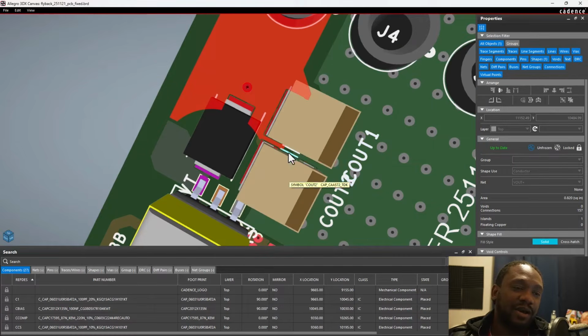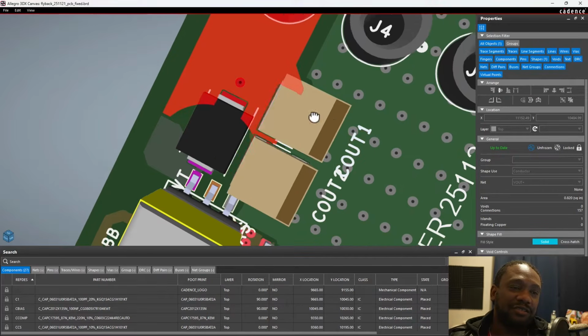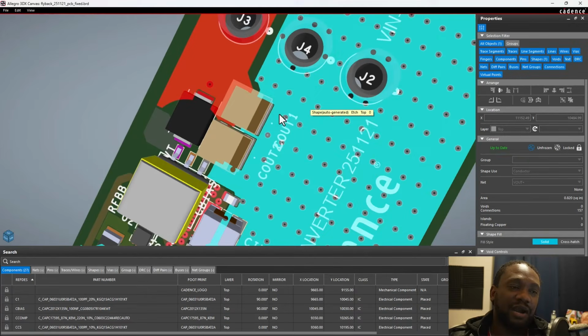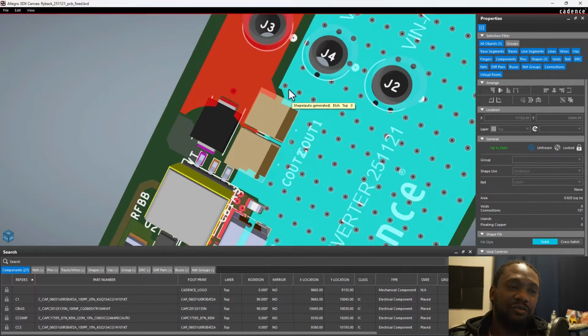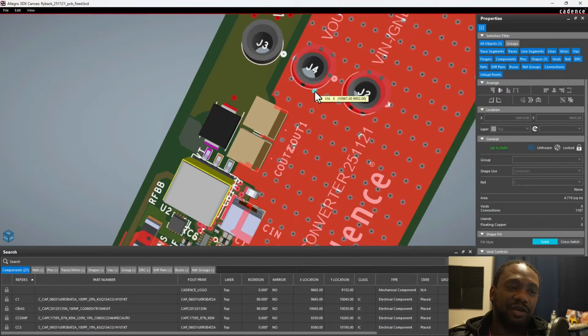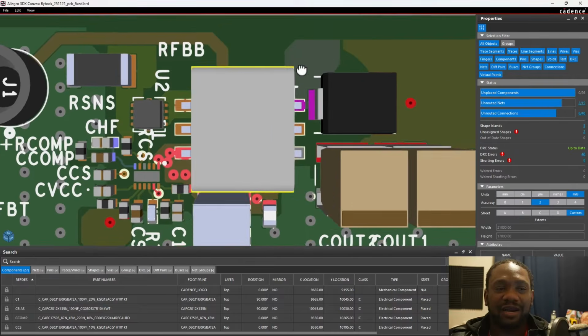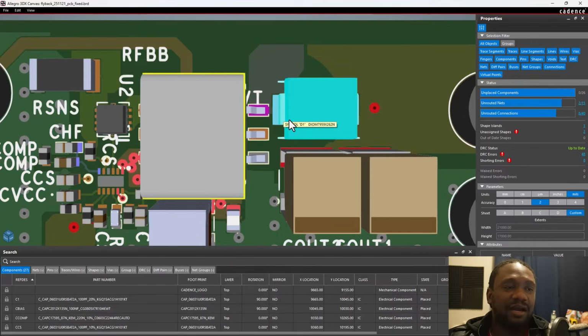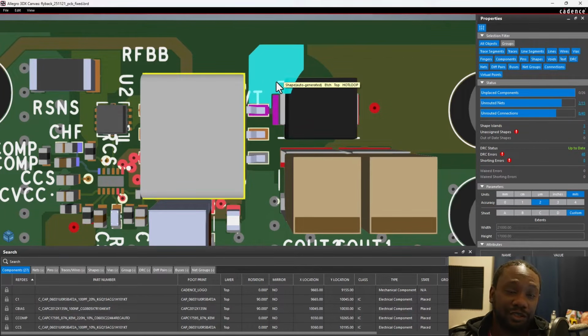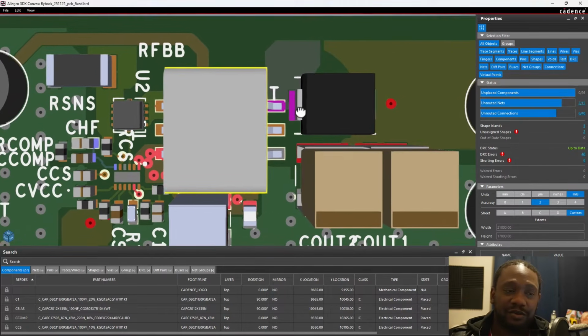And see here are my two output capacitors, and then ground for the return path of that hot loop area number 2. Between the primary side of the transformer and the secondary side, I can establish a creepage constraint. That can be done using a keep out area or zone, or your constraint manager to enforce that rule. You'll do it based on your safety standard, whether it's 2.54 millimeters, 6 millimeters, whatever your standard says.